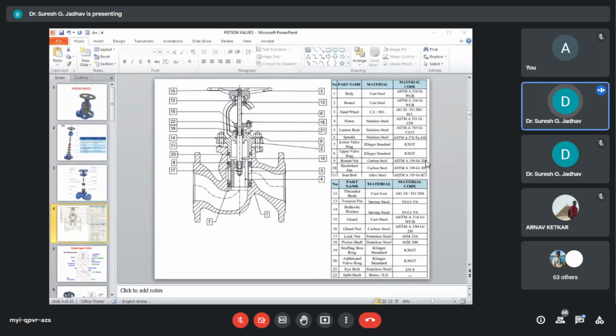This, along with the resilient sealing rings, produces a spring action, which compensates for any differential expansion that can occur in the piston valve rings. So we call it the differential expansion that occurs. Therefore, we can consider different types of stem designs available in piston valves.